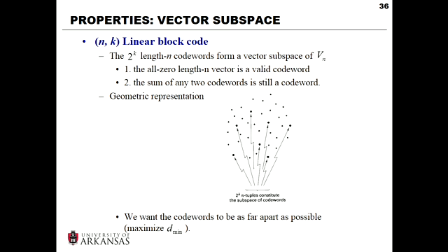Okay, so optimum soft decoding is to minimize the Euclidean distance. And also we have the optimum hard decoding. For optimal hard decoding, once we receive the information, we first quantize it into ones and zeros, or ones and negative ones. So we have a binary sequence. Still following exactly the same maximum likelihood principle, we found that it's equivalent to minimizing the Hamming distance. So we either minimize the Euclidean distance or the Hamming distance, depending on whether our information is soft or hard.